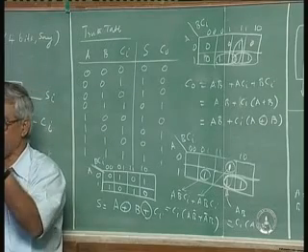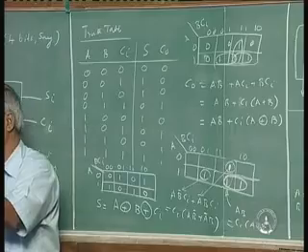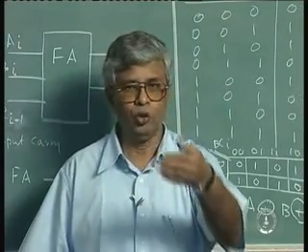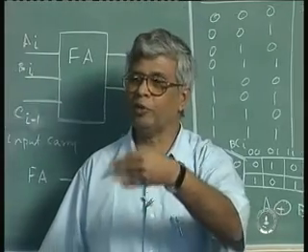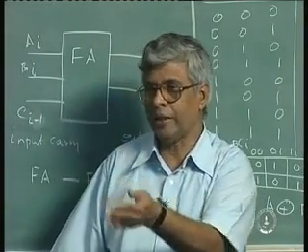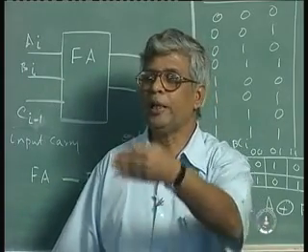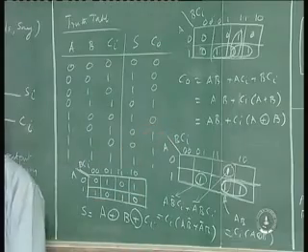You will have to say 8 3-input AND gates, 6 2-input OR gates, 4 4-input OR gates. Like that you should give a list of type and the number of inputs. Only then it becomes complete. It is as if you go to a market with that and buy those. Make a shopping list of the number of gates required to build a 16-bit full adder.